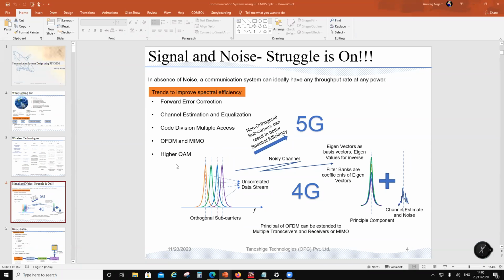Now, what you can also do is, instead of transmitting the bits, you start transmitting symbols. So if I club 2 bits, that makes a symbol. Now I have got 4 states. If there are 2 bits, I have got 4 states or 4 bins. So I can decide what should be the amplitude of the carrier and what should be the phase. So that's your QPSK, right?